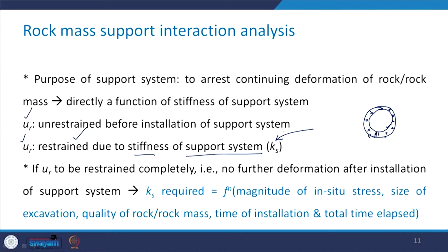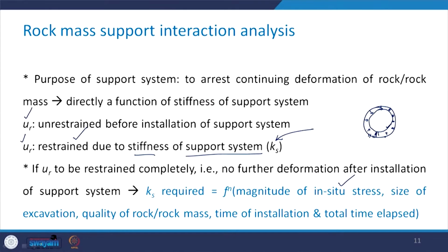Obviously, the stiffness of the support system Ks which is required will be quite high, and therefore, the required Ks becomes a function of the magnitude of in situ stresses, size of the excavation, quality of the rock or rock mass, time of the support installation, and the total time that has elapsed.